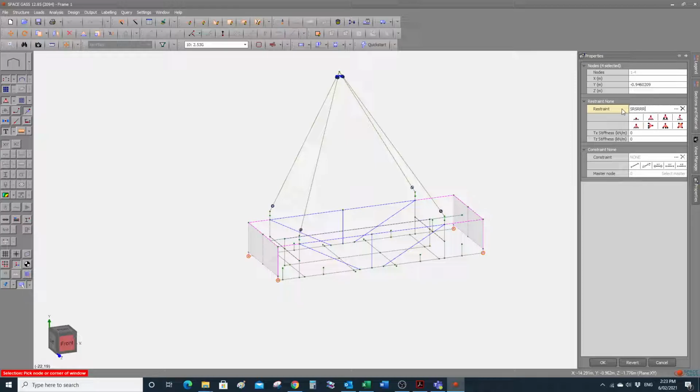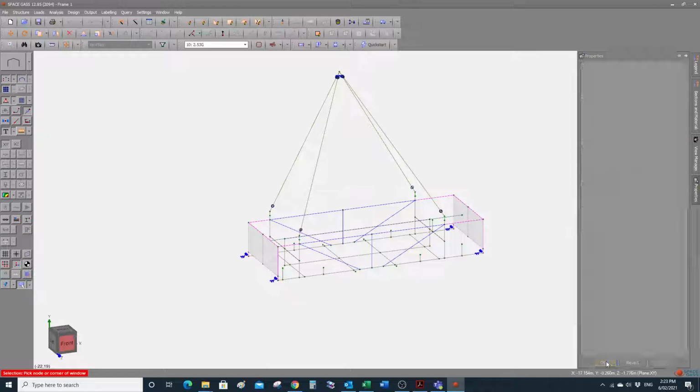is by soft springs. So basically, I model soft springs at four corners. I normally choose four corners because I know that this way I can completely stabilize it, and I apply very small stiffness. I normally apply 0.05 kilonewtons per meter stiffness at X and Z, which are horizontal directions. Of course, if you have different units or your software has X and Y, for example, horizontal, you have to do it accordingly.